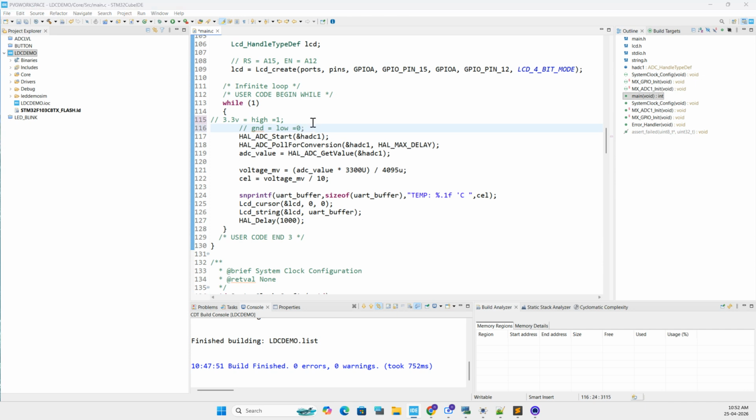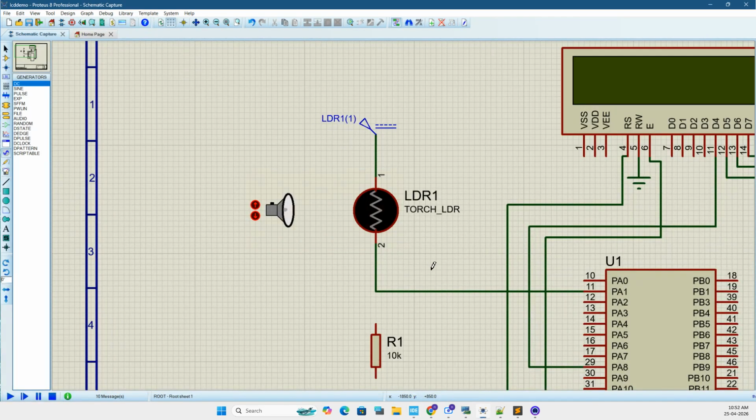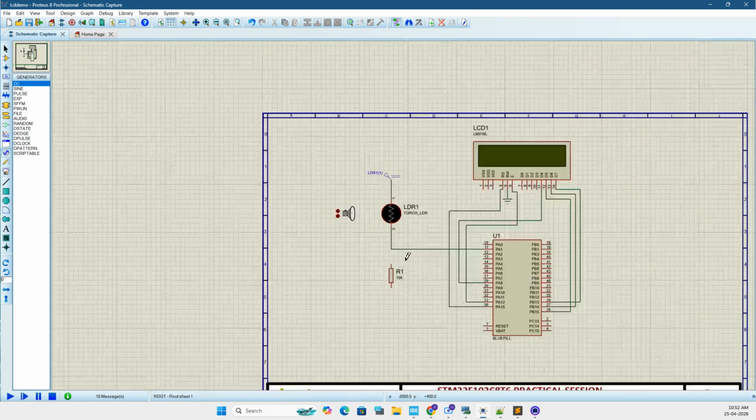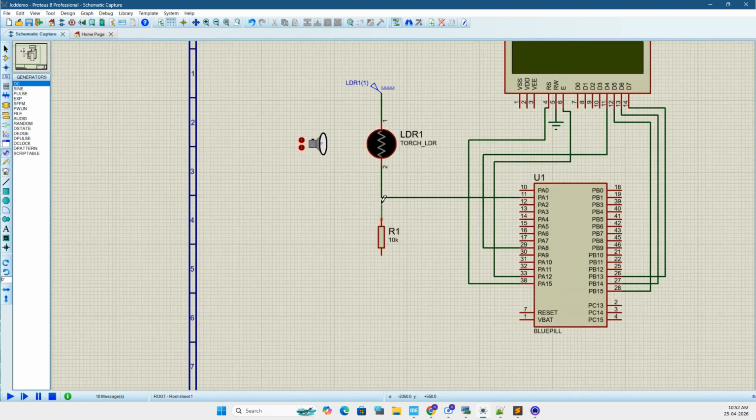So you cannot keep the pin open. It is going to go into a toggle state, or floating state. So for that, what this resistor is going to do is provide the ground after the switch is released. This one is going to provide the ground, or 0, to this PA port.